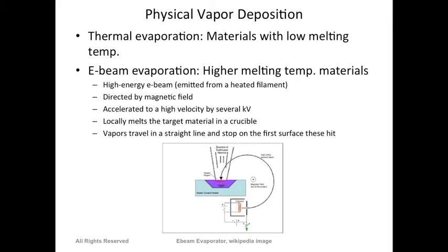The furnaces are very similar, but with E-beam we can normally achieve higher temperatures more efficiently compared to thermal, voltage-based or current-based heating. In these E-beam evaporators, you can deposit almost all the materials deposited with thermal evaporation, using the same target.